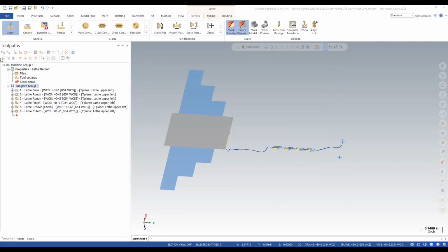I want you to verify all your X's are positive. Why is this the only negative X on the first pass? It's the face pass. It's got to go across center, the nose radius value, the nose diameter value. So it took the nose radius and doubled it. The 03 is a 06 now. So that's why you get that 1/8 of an inch right there. Does that make sense? So that's the only time you should see a negative X. All your other X's should be large, like 1.7 to come in, 1.5, and you should be getting smaller as you go down, right?